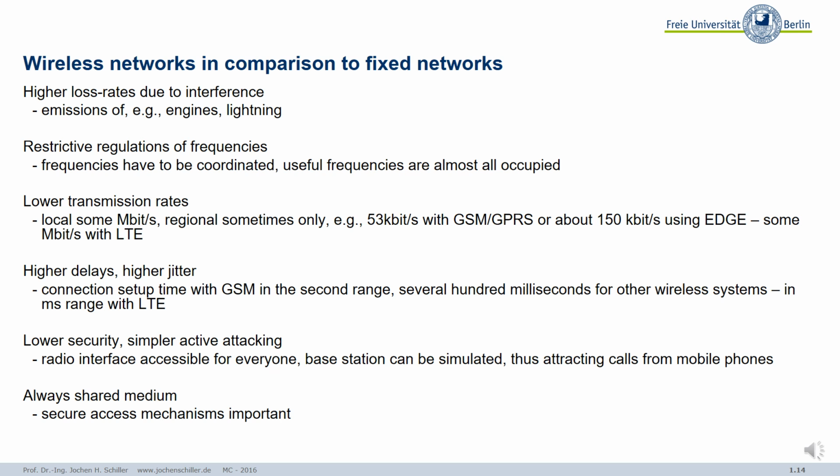This introduces some delay. So you always have higher delays. You always have lower security because, as you saw, with such a simple device, I can easily eavesdrop into all the frequencies. No problem at all. And with software-defined radios, for some euros, you can build your own GSM base station. It's no problem. And as I will show you, not all of the systems are really protected.